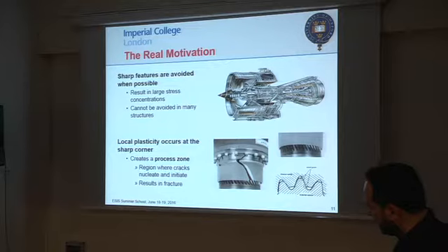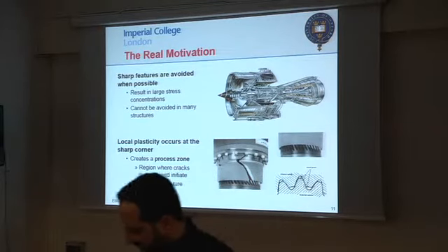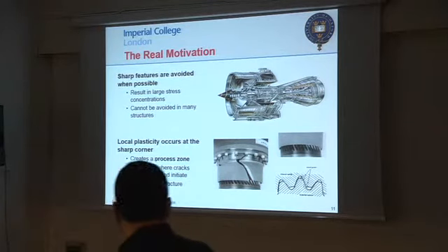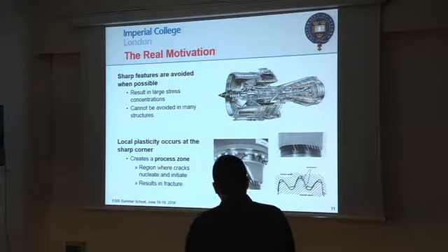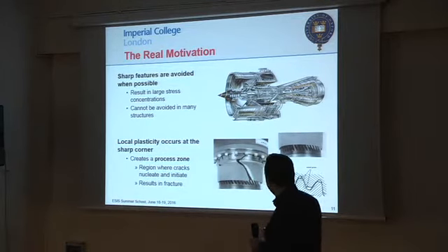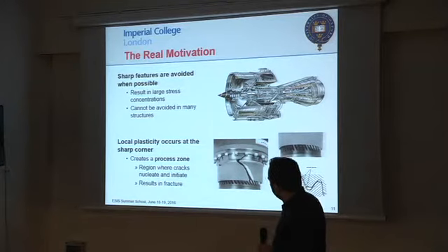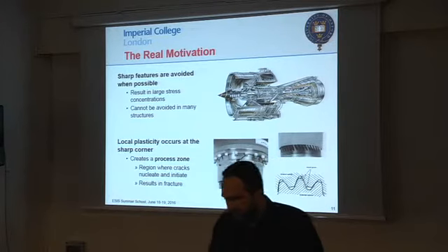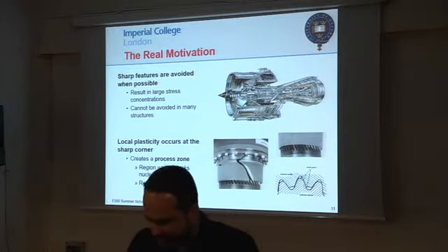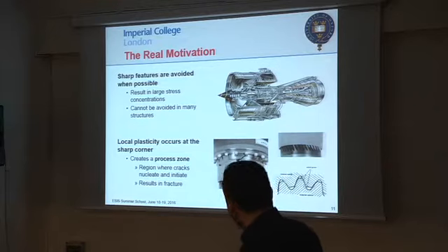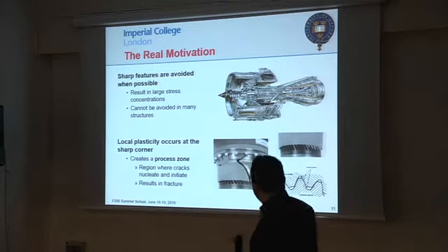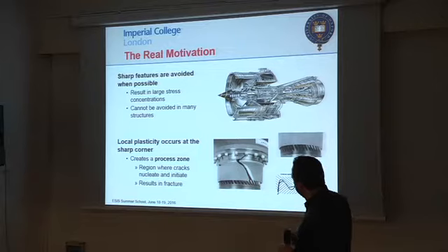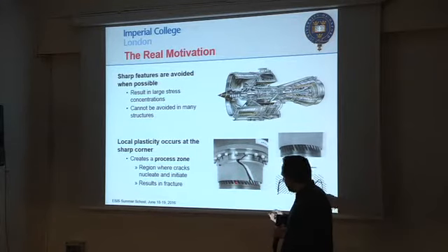Now, the real motivation of this talk is back to my PhD. Working on those engines, as I've just shown you before, trying to understand some of the issues that you might have if you have stress concentration, if you have elements in which you've got either contact or sharp features that result in large stresses. So for example, one of them I showed you already is the fan blade attached to the disc. Another one is when you have two shafts.